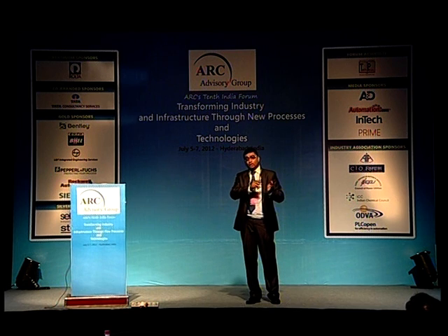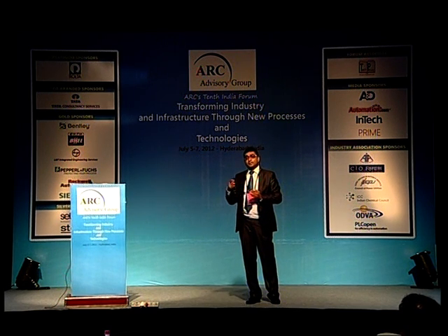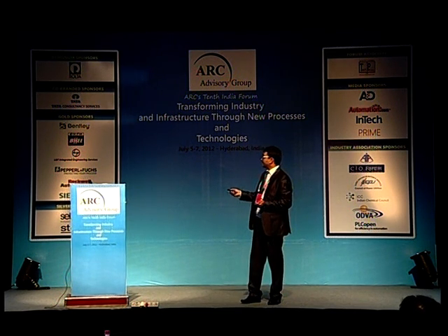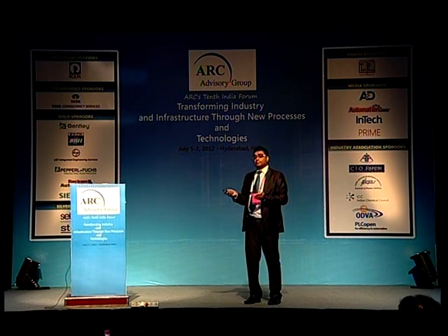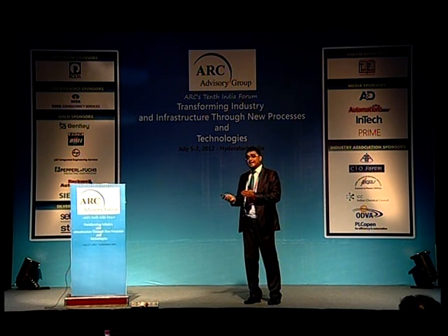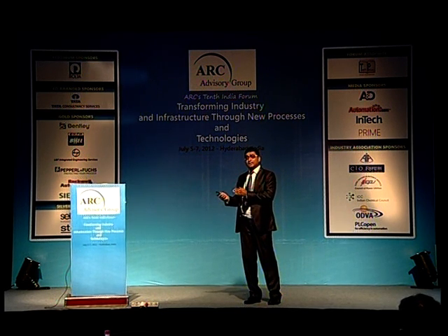If it is continuing for a longer period of time, then you can have a look at that particular tube and that particular area during your annual shutdown. So that gives you a direct indication. It is not directly a leakage detection module, but it can give an indication that if this particular hotspot is happening for a longer period of time, it can cause a leakage.